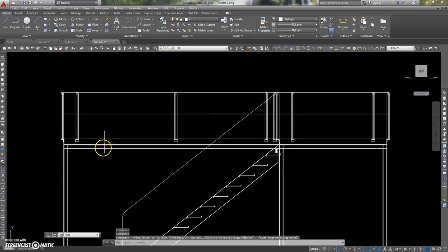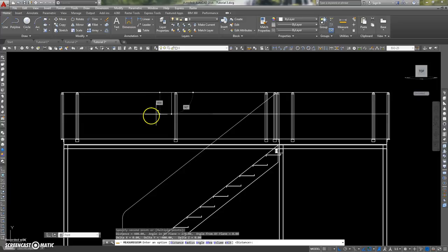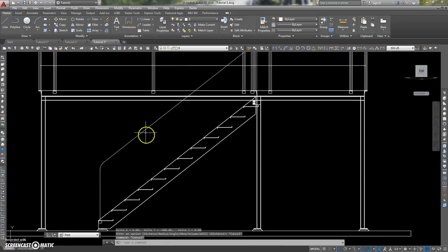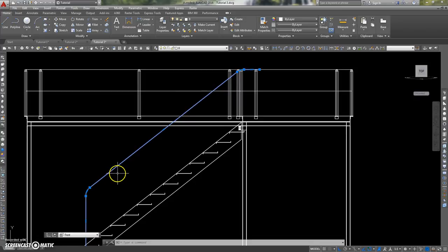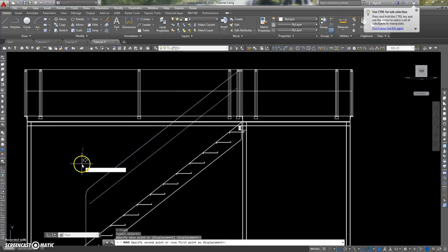And what do we make? Move from there down to there, 400. So that now is going to be a nuisance because it's got this bit extra on it now, and it's turned itself into a bit of a polyline. So I just do a line from here to there and move the last thing you drew down 400